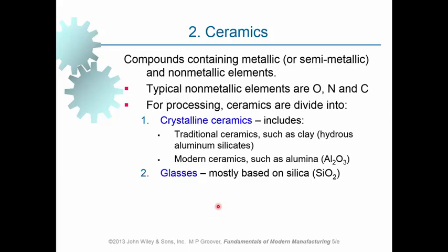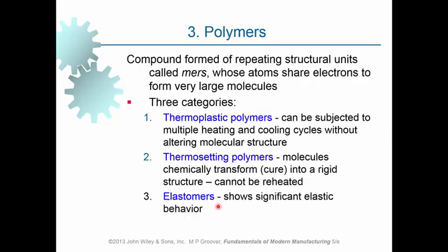So they are frozen in a way that there is no time for the atoms to sit in the right place in the structure, and there is a lack of order in the structure. So glasses haven't got a crystalline structure, and they are referred to as amorphous materials, and this provides them with the possibility of having a lower density compared to crystalline ceramics, and because of this there are some void spaces in between. The density is lower, and this also contributes to the transparency of glasses.